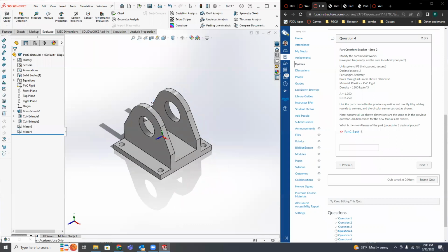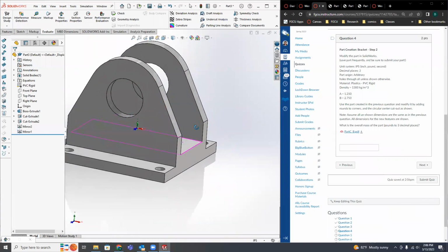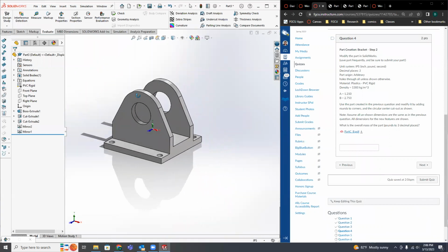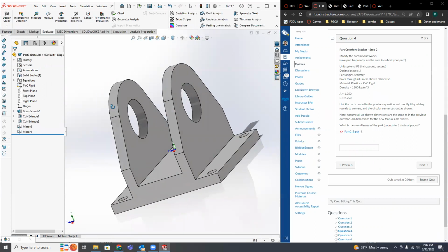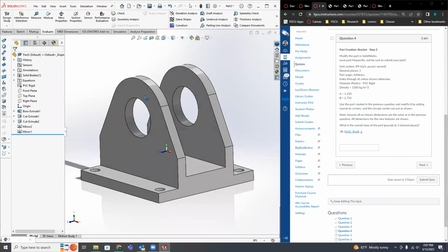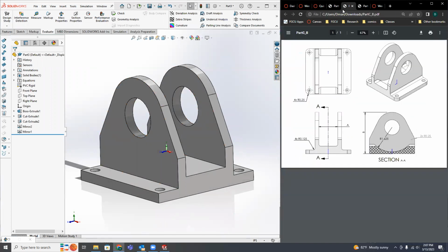And you can see that my drawing did update. It got a little bit stouter. You want to make sure you do that before you start making too many changes, because you may have errors you need to resolve when you change A and B, depending on how you've made the part. Hopefully you've made it in a reasonably resilient way that doesn't cause issues, but you want to fix those before you add more complexity, because it's gonna be harder to fix it once there's more complexity there.